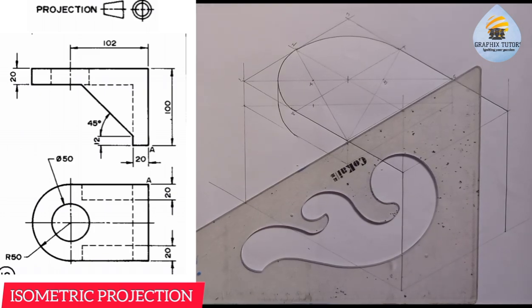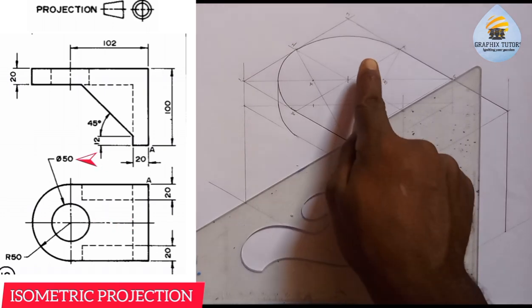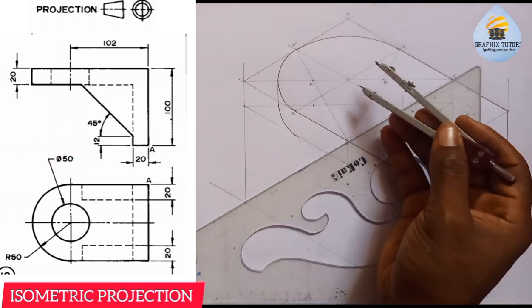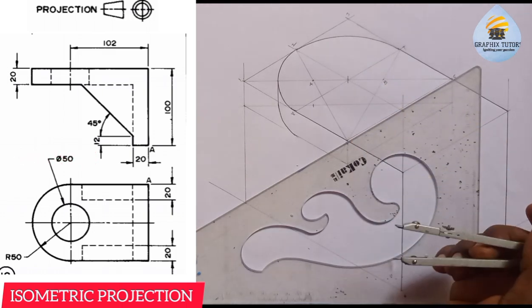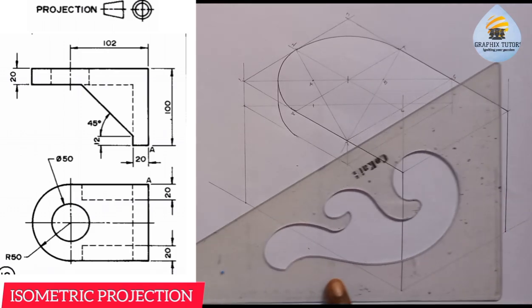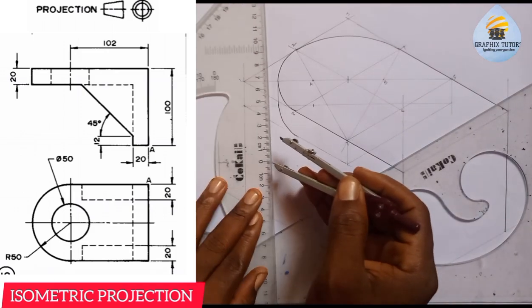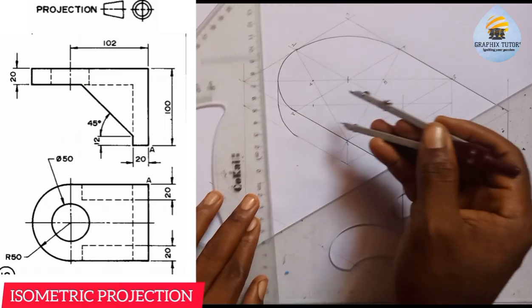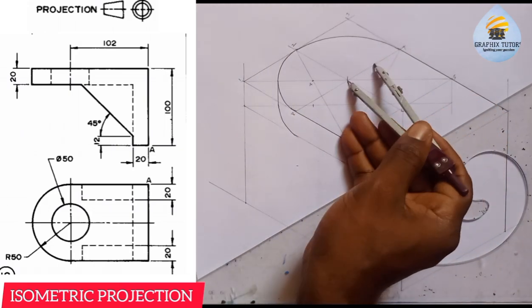So we'll move forward. Now the next one we're doing here is the circle in between, which has a diameter of what? 50. So I'm going to construct a circle in between here. So measure 50. We know that this is a diameter of 50. Half of it is what? 25. So I'm going to measure 25 on my meter rule. So from 0, 25. Now I'll place it here. Strike an arc.